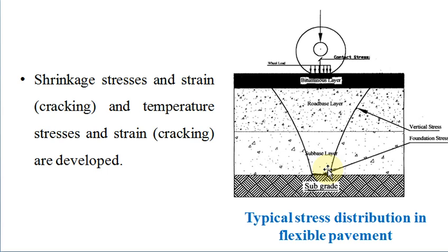So this was the basic concept which was being followed by Boussinesq, that the effect of the loading with regard to the vertical stress will be prominent at a shallower depth, that means at the top layers, and at a depth of infinity or at a certain depth this vertical stress diminishes. That means that vertical stress becomes zero.